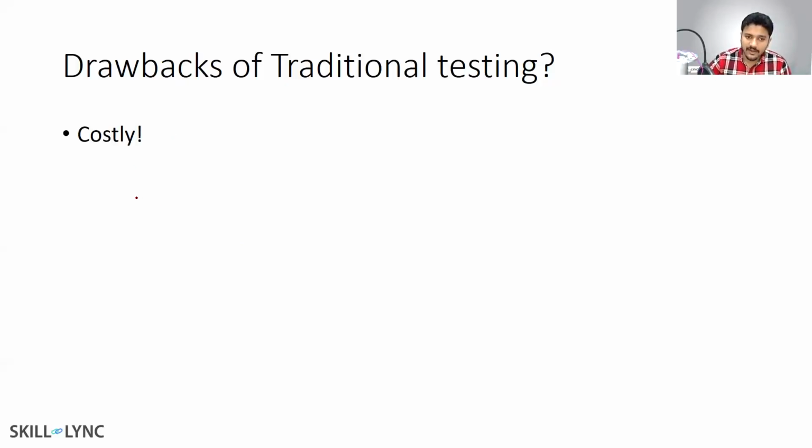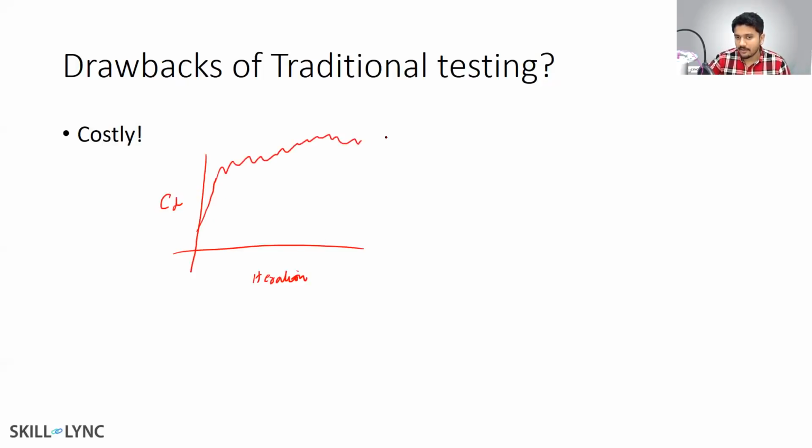Let me explain that. Say this is iteration, and you're looking at drag coefficient. Initially the drag coefficient can be 0 when the simulation starts, but after some time it goes up and then starts doing this. You need to wait till this happens, and then at this point you can take an average. This average value is going to be your CD. The average CD should vary very little, exactly. And this is basically your baseline.